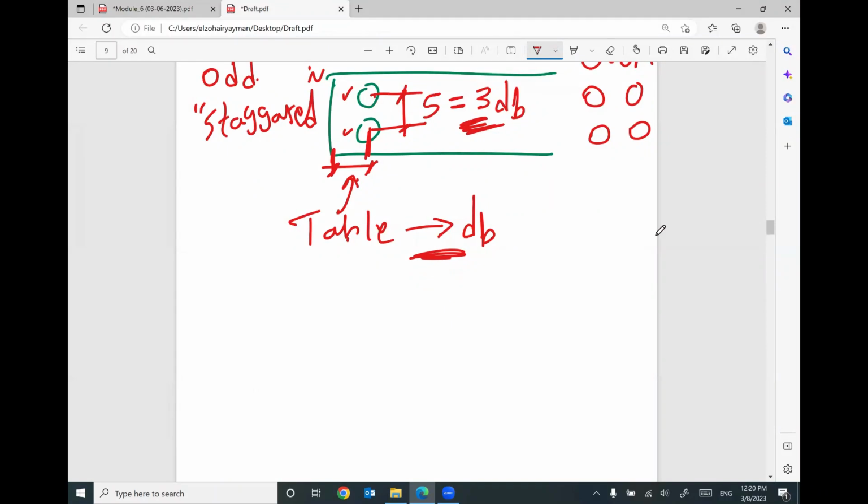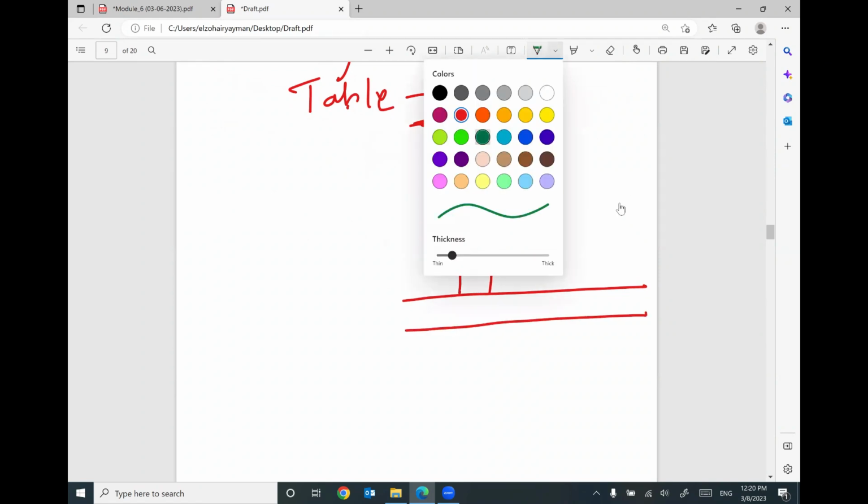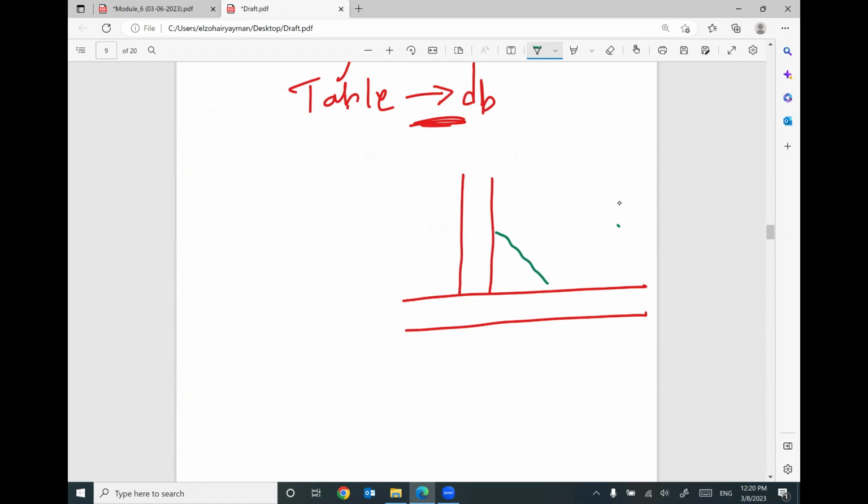So, for example, if you have welding between these two surfaces, and your welding looks like this, and this horizontal distance is 1/4 inch, and this vertical distance is 1/4 inch, I can say W equals 1/4 inch, and this W is called weld distance.